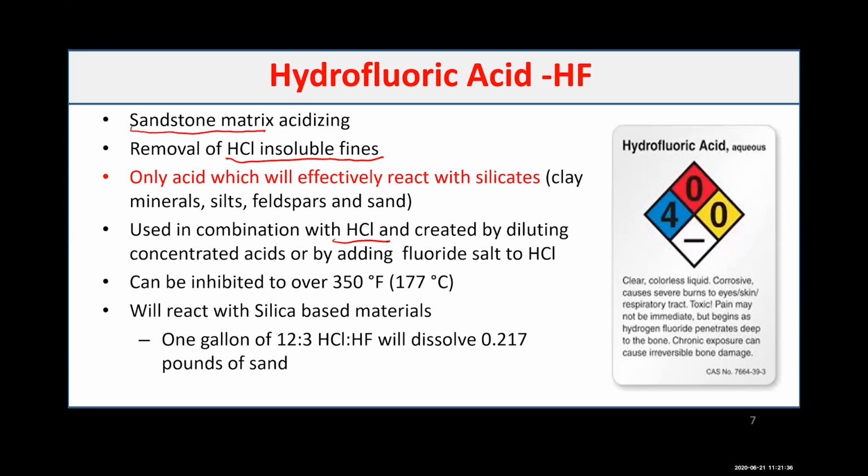Therefore, when you are talking about sandstone acidizing, you need to be really careful about how you're designing your job. What's the post-flush and pre-flush that you're pumping, and how you're pumping your job. And definitely, as I said, don't pump HF until you are extremely sure that you have a damage that needs to be removed by HF.